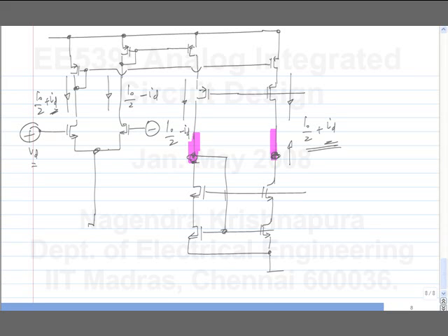So because in this case you fold the current that comes out of the differential pair, this is known as a folded cascode. Yeah, current is folded down. So this we will discuss in detail, and actually there is another way of making a folded cascode. Okay. Again, I think I am out of time, so I am going to stop here. In fact, this current mirror is not what is frequently used. Okay. We will discuss the other technique tomorrow. That's all for today.